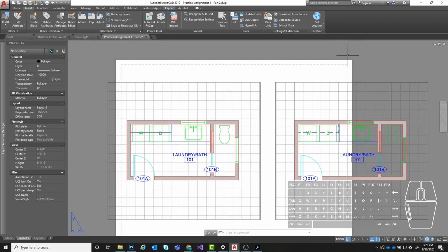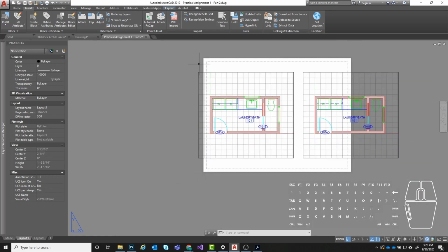Anything that is outside of this white piece of paper is obviously going to be cut off and not printed. So that is the boundary of our piece of paper, this white that's out here. But you can make viewports and put them anywhere inside of this gray space. Just know that anything that is not on this white sheet of paper will not be printed out, okay?